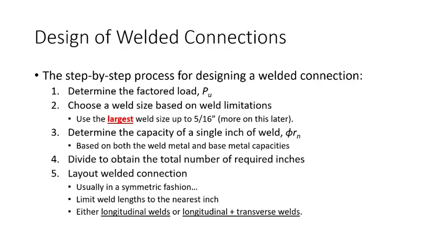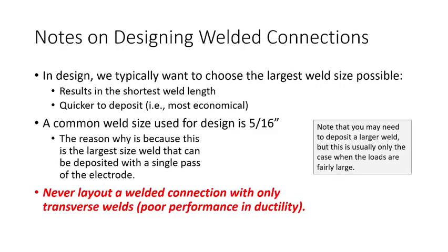And remember, when we lay out our welded connection, we utilize either longitudinal welds or longitudinal and transverse. No transverse by themselves. Yes, sir? Is it nearest inch or the inch? Inch up. Inch up. Yes. So if you compute that you need 10.2 inches, round up to 11. Like that. When we lay them out, again, use longitudinal or longitudinal and transverse. Don't use just transverse because that's a ductility issue. Okay.